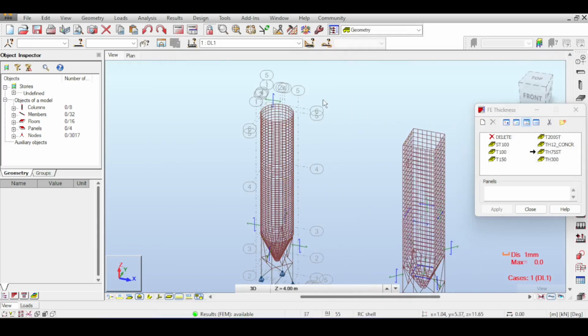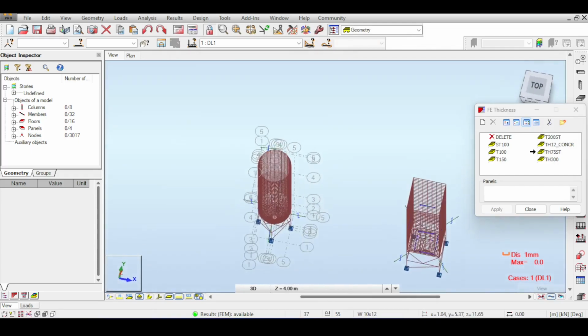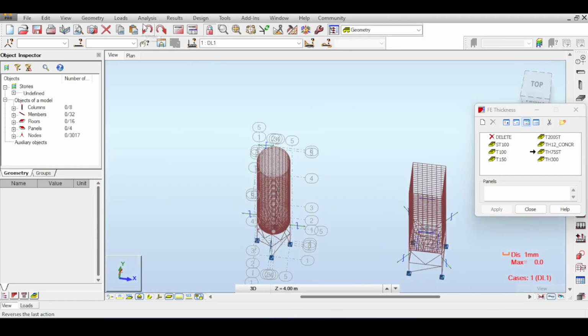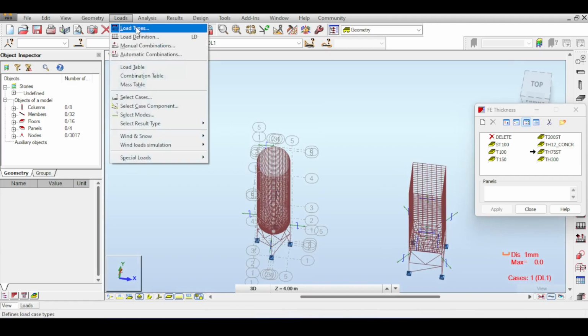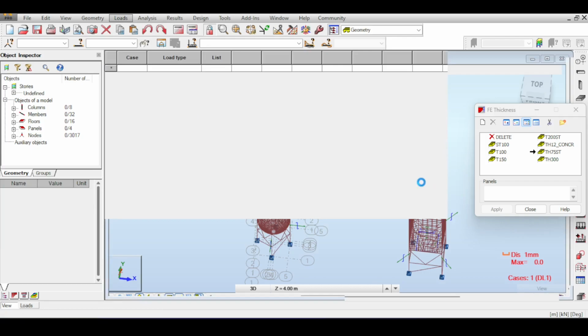So deflection shape, of course, I need to check out my deflection shape. Oh, yeah, you don't have loads at all. I totally deleted even the self-weight, I think. Let me just check the load table, which is incorrect, by the way. I should add the self-weight, at least. So taking a look, yeah, the load table is totally empty. That's incorrect, so I have to go back